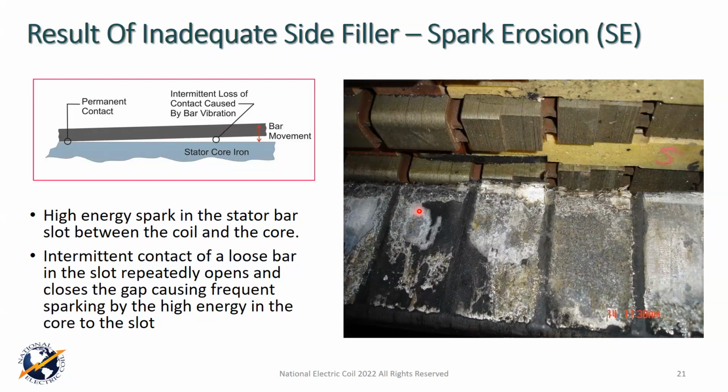It didn't just settle down in there, it actually shrunk. And most epoxies, even when they're fully cured, in stator coil applications, it's very common for them to shrink maybe as much as 1 to 3% over the first couple of years of operation, and then they'll stabilize. But because of that, when you wind these machines, if you don't have some resiliency to keep that coil tight in the slot, it's going to move. And if that coil moves, this is the phenomenon that you may get.